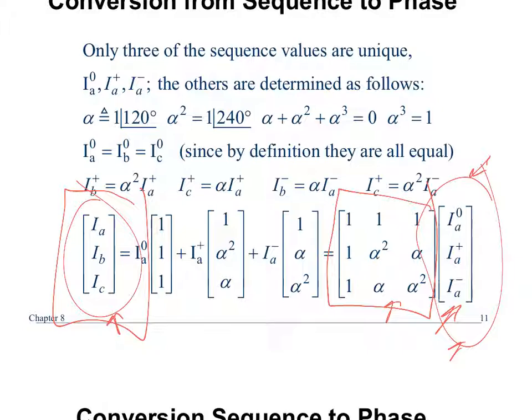Now, if you're designing a system, right, and you're trying to set the protection elements up, the relay is going to have the phase currents, but you have to set the elements to trip based on certain parameters. So when you do your upfront analysis to figure out when do I trip, when do I not trip, you actually have to do all the calculations to solve for these.